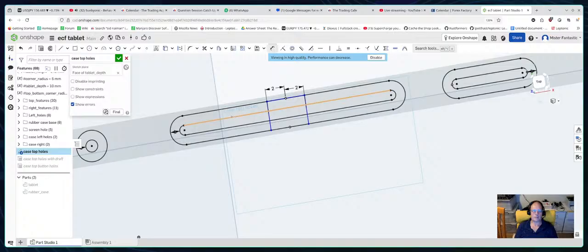So they're going to be the extrusion, and then we're going to go this, this, this, this, offset again, 0.5 mil. Other way. Need 0.8. So we'll have a 0.2 mil gap between the actual hole and this thing. That seems legit. Okay, done.